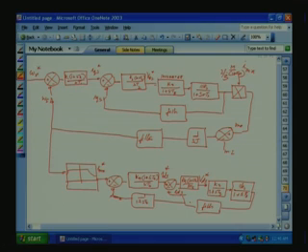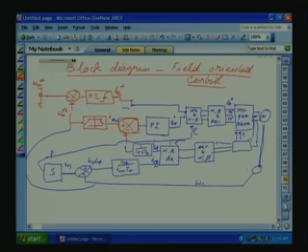So this way we can have a vector control. But the most important thing is the rho, the instantaneous position of rho. If rho is correct, field orientation is correct, then we can use this closed loop control block diagram for designing the control parameters. So the most important thing is finding out the rho. As I told before, a tacho or a position encoder is required, then slip is required, slip you have to add and integrate, rho you will get.